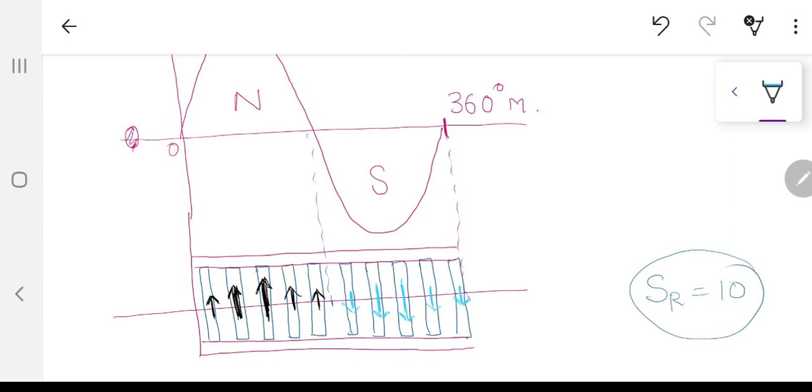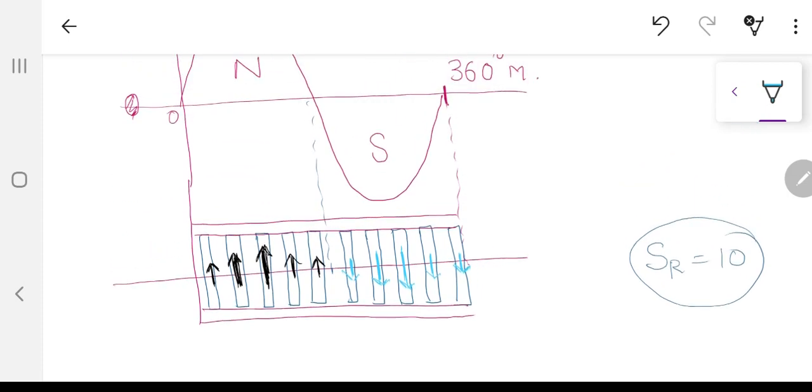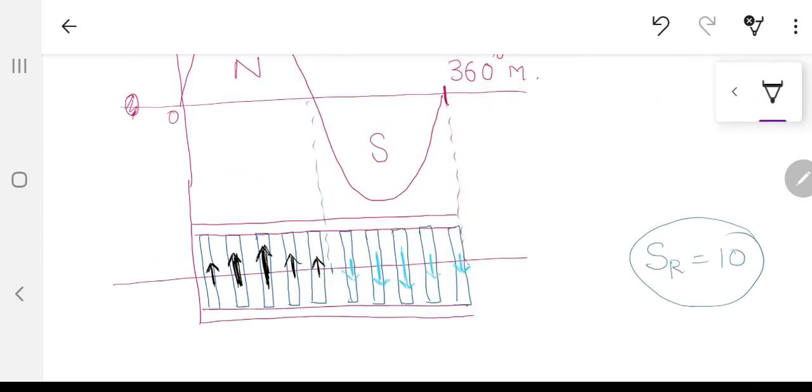Now how are you going to find out the end ring currents? Because we have found out IP as an RMS value. Now here, since we have assumed that these currents are going to be flowing inside the bars, the end ring currents are very, very important. Before I proceed towards the numerical equation, one thing has to be decided very importantly. This current which is flowing over here is going to be flowing over here, and this is going to flow like this.